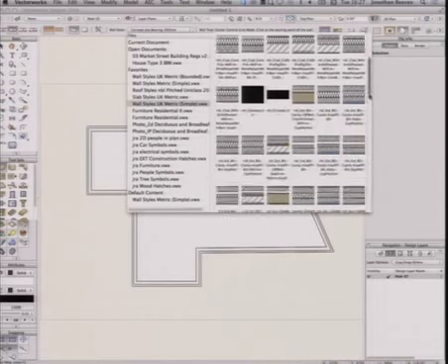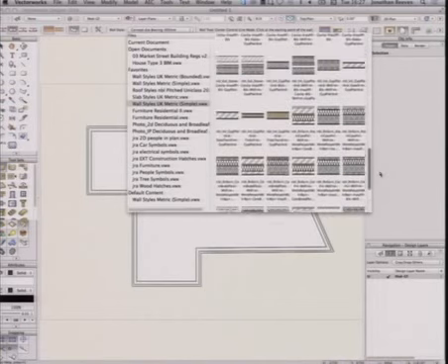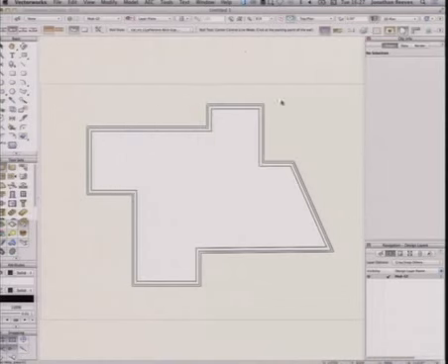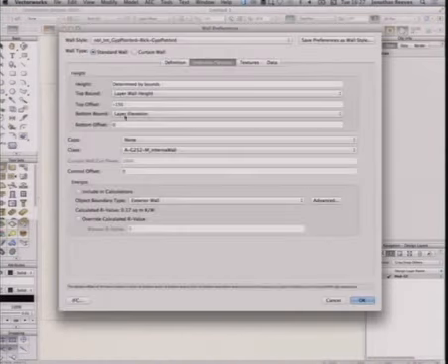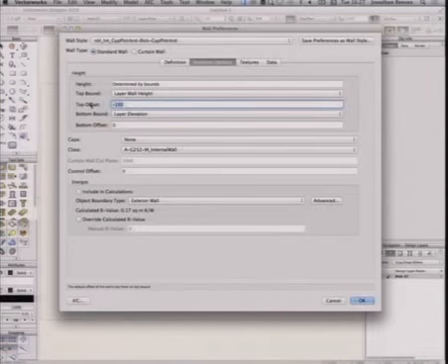So let's go down and choose, this time, from my vast array of wall types, some internal walls. Just quickly whiz into the settings, and I'll just make sure the settings are correct in here. So really the key here is I want to have these internal walls linked to the layer wall height, but I might only want them to go up to the underside of slab. So I will give them an offset value to bring them back down again from that 2700. That's fine. I'm going to just basically save that as a wall type.